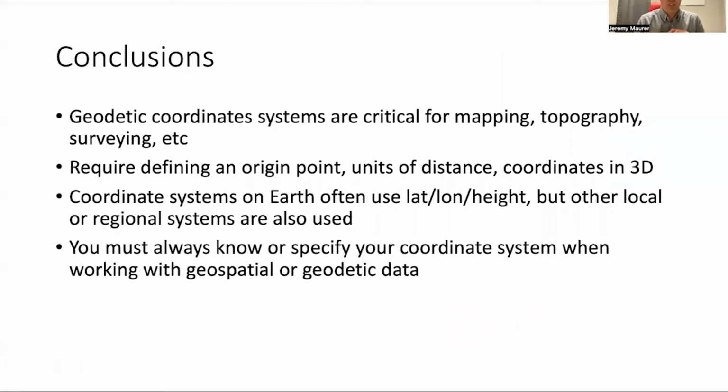Okay, so these geodetic coordinate systems, reference frames, datums, it's absolutely critical that you know what reference frames and what coordinate system you're using. If you're just using latitude and longitude, it's pretty easy. WGS 84 is the most common, but you need to be very careful about heights, and you need to be very careful if you're switching back and forth between UTMs, latitudes and longitudes. Make sure you know what coordinate system you're using at all times.